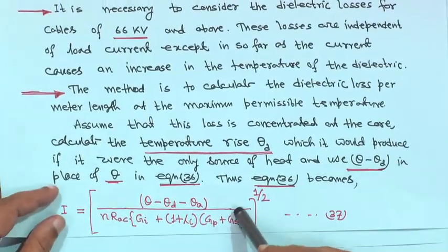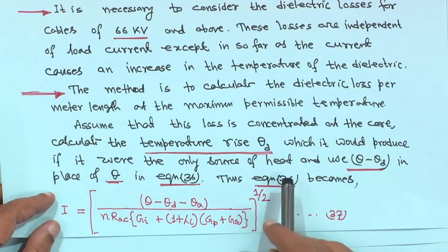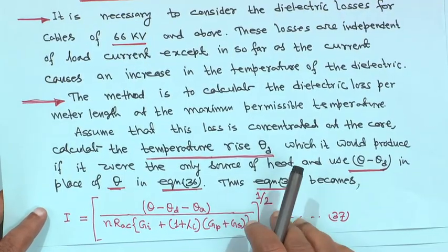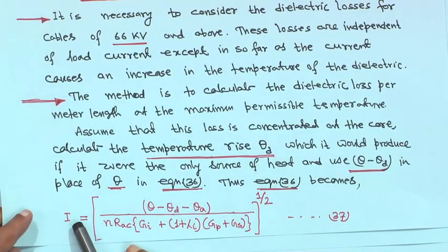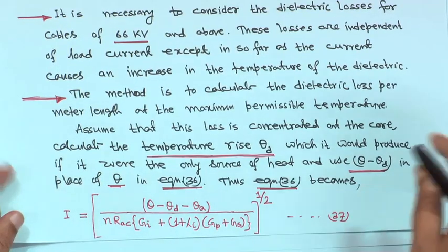So, that means in a cable different losses are there, and that will cause the temperature rise. There is a maximum permissible limit for the cable temperature. So, your current rating has to be restricted till it achieves the maximum current rating, not more than that, right.